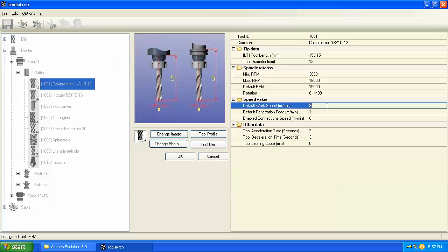The next parameter is the feed rate. Like drills, these parameters, lengths and feed rates, are in metric. When we get to feed rates, we're talking about meters per minute. If you think in inches per minute, like a lot of us here in the States do, then a quick and dirty factor to go from meters per minute to inches per minute is 40. It's actually 39.3 or something like that. But if you just use 40, then 8 meters per minute is loosely equivalent to 320 inches a minute.